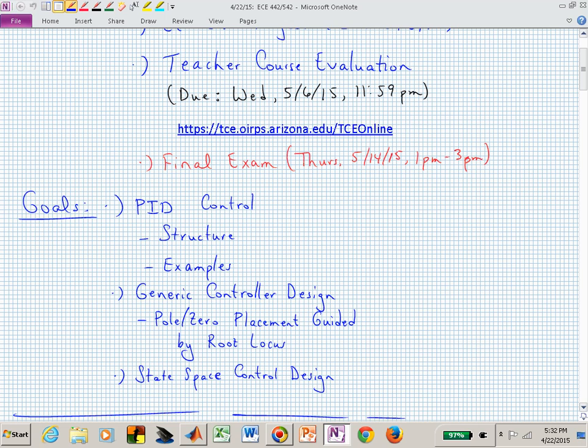But I'll quickly scroll through that, and we'll spend more time on the examples of how we really place the two zeros that are now available to us in the PID controller design. That's the flexibility we end up having: placing two zeros if we use all three terms, the proportional, integral, and derivative term, in the PID controller.